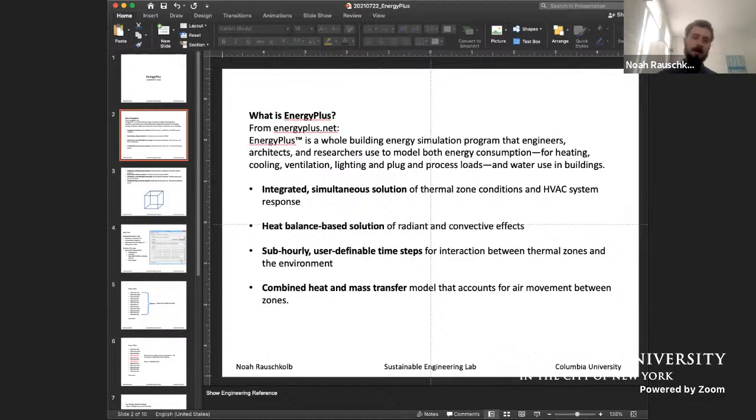When we're engineering air conditioning systems for buildings, we're always working around both. If you've got a building with a lot of occupants, there's a lot of moisture being put into the air. As humans, we produce about as much latent heat as we produce sensible heat. And you're always trying to take out both the sensible and the latent if you're air conditioning.